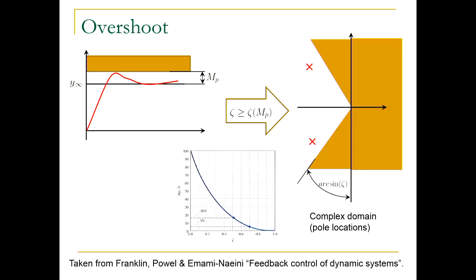If you apply too much current, then you would push this thing too far, and you will hit physical boundaries, and you might damage things. You would hit things with physical limits with certain force. So you may want to have 0 overshoot. You don't want to hit this with a huge force, right? There are lots of other examples where overshoot is just not desirable.